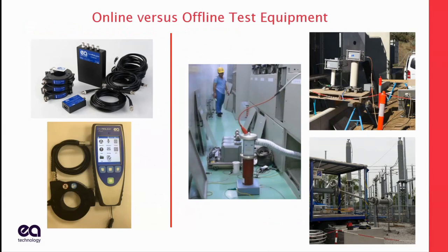One big advantage of online versus offline testing, the number one advantage of not doing offline testing, is you don't need an outage. You don't have to convince the operators to let you take this cable out of service for 4 hours. But the equipment is a lot smaller. So when you do an offline test, you still need to energize the cable.